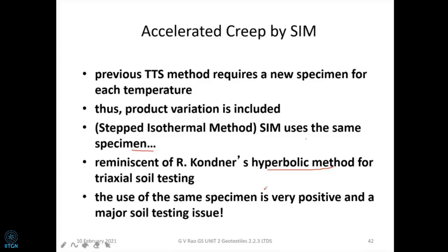Now, what is the hyperbolic law? It means that you have a regular symmetric curve. We have the compressive strain on the horizontal axis and the vertical stress sigma. So sigma divided by the strain is going to give you the hyperbolic plot in a linear scale. Once you get the slope of that curve, we can find out the ultimate value, that means the maximum strength which we are going to get. So at that confined pressure, we are going to get that estimated failure value.